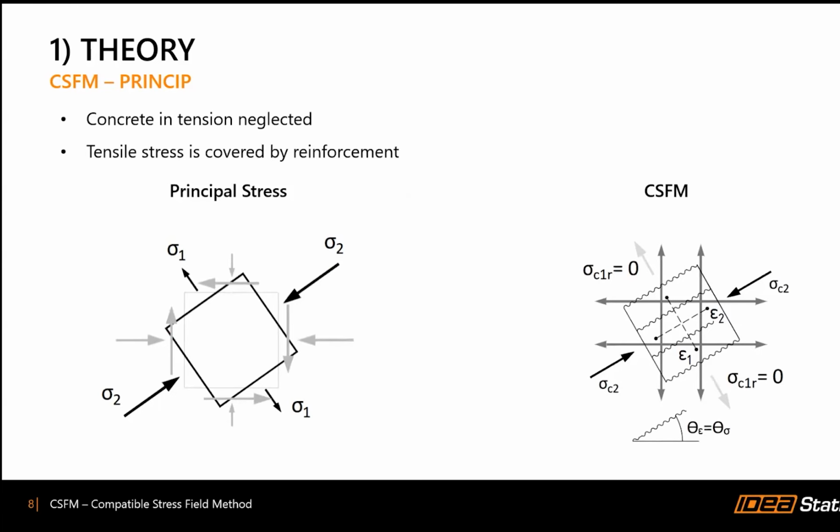It means that it's a material nonlinear analysis. We are neglecting the concrete in tension, and everything in tension is covered by the reinforcement. The tensile stresses are covered by the reinforcement, as I mentioned. So it's very important to say that. And this is the code compliant method.